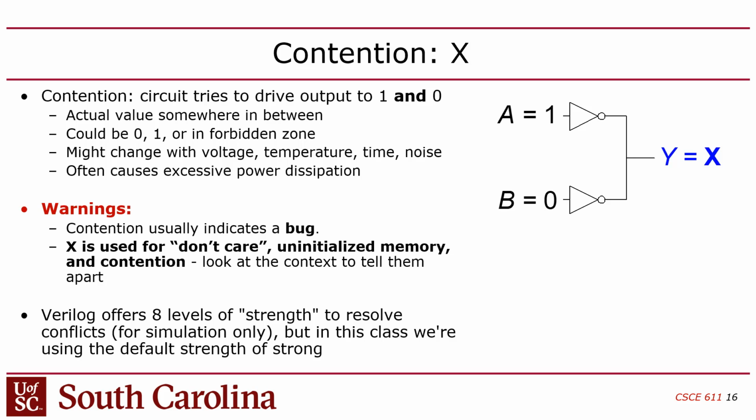You want the voltages to be discrete, right? Now, if you're looking at this from an analog perspective, that's fine. You can tell if it's happening because you look at the analog voltage and say, it's 1 volt, it shouldn't be, that seems weird. Something's going on there, so we must have double driving: two gates driving this wire to two different values. But the problem is we're not doing analog simulation in this class. We're doing digital simulation only.